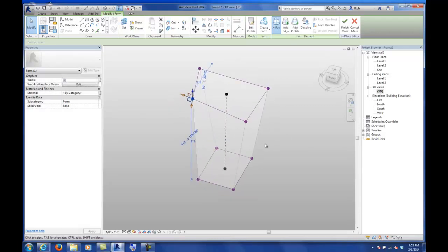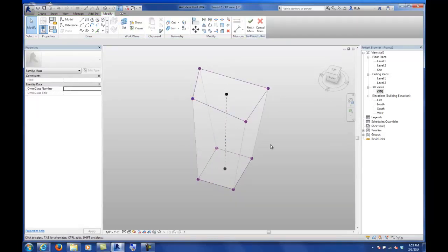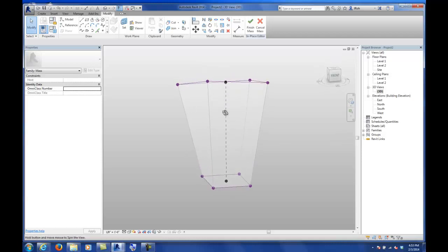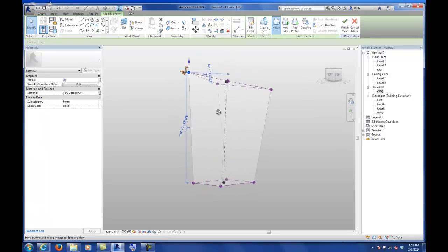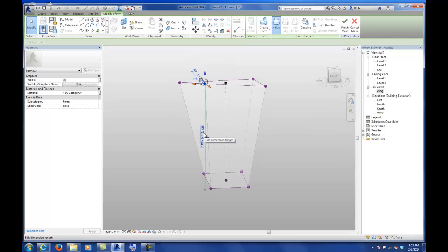Jeremy, do you know how it's resolving that top face right now, since it's not a planar surface anymore? It is always lofting. It's basically interpolating what this form has to do in the loft in order to get to the next edge. Right, so the vertical one will be a ruled surface? Mm-hmm. But the top one is a warping plane. Yeah, it's warping. So it will leave it as a NURBS surface at this point? Right. Not triangular. It's all NURB modeling in this intuitive massing. Okay, good.